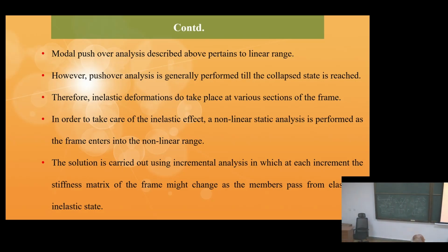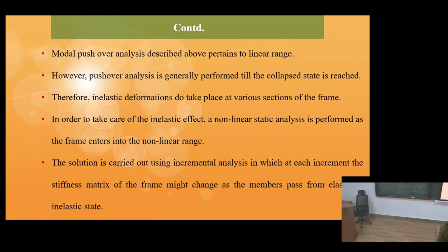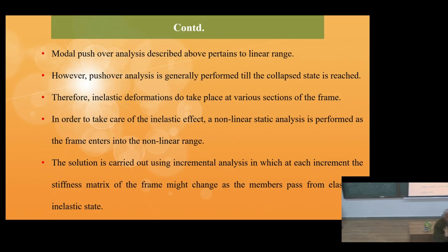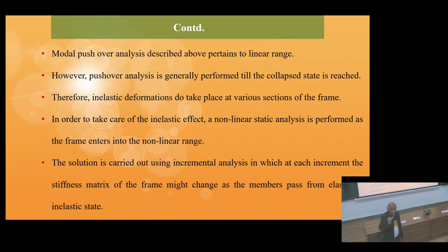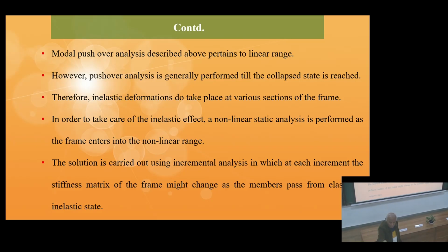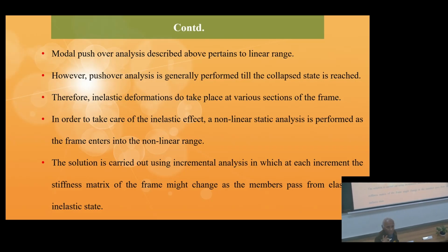However, pushover analysis is generally performed till the collapse state is achieved. Okay. Now this collapse is defined in terms of displacement. Okay. Because it is now displacement control. And you know what you mean by displacement control now. So that means we push up to a certain specified displacement, and that is our collapse state.